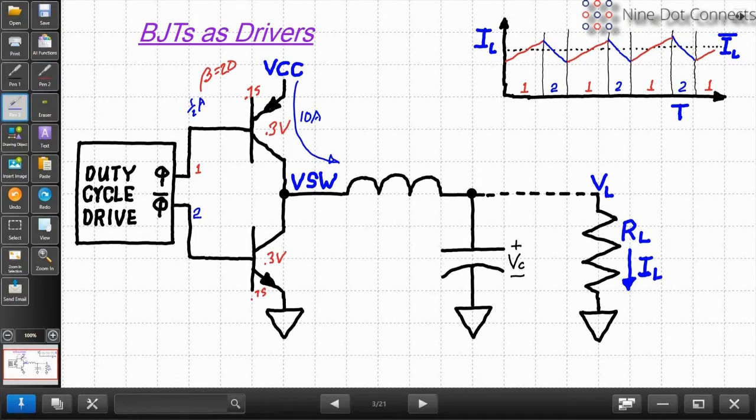Okay, but there's even one more significant problem. If we have inductor current flowing out through the inductor, it's going to keep flowing. We'll typically be switching much faster than the time it would take the inductor to completely run out and stop. So if we suddenly alternate, we have our time number 1 where we're switching in number 1, and the current is ramping up. But at time number 2, the current is ramping down. Where's that current coming from? The upper switch turns off. Instead, the current needs to come up through the bottom switch.